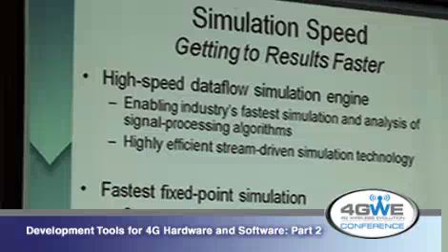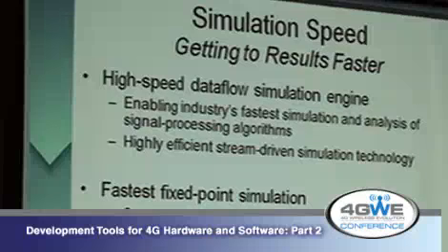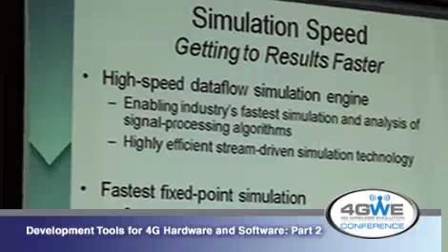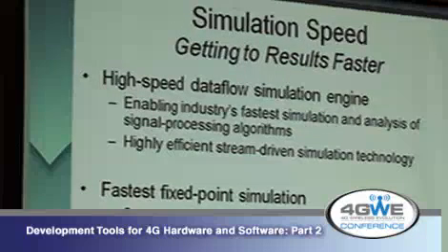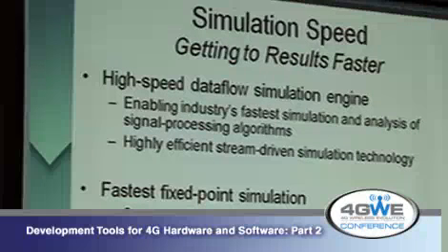It's a stream-driven simulation in the data flow domain, where a lot of it is taking one block which fires a certain amount of elements, connecting to another block which can execute and consume a certain amount of data in a certain amount of time. We do pre-scheduling in advance of the actual simulation, so there's very little discrete event simulation going on by having as much pre-scheduled as possible.